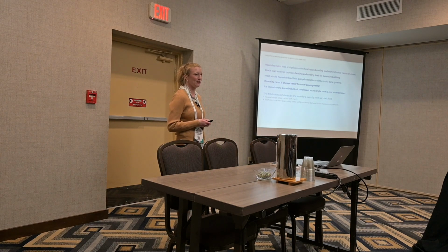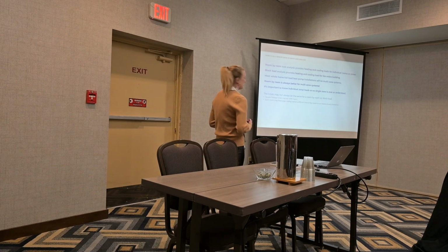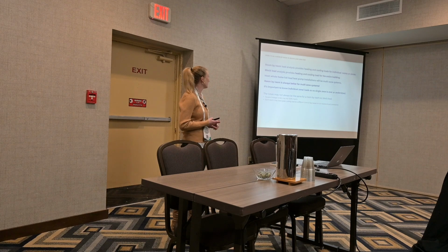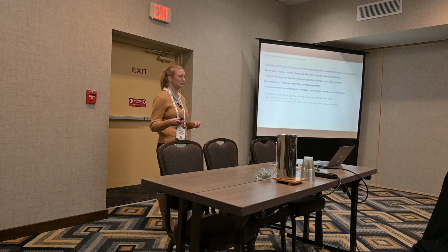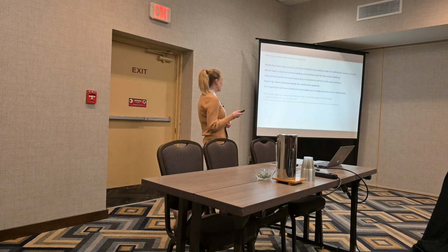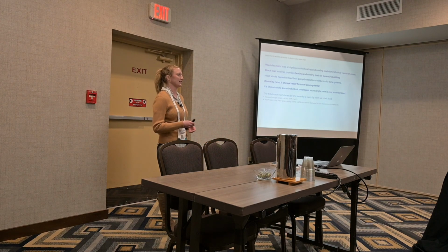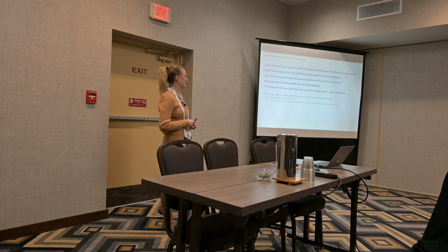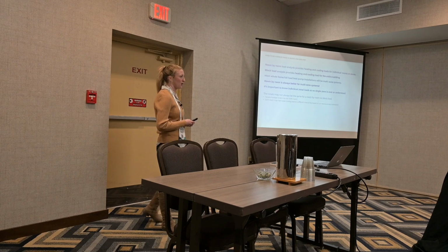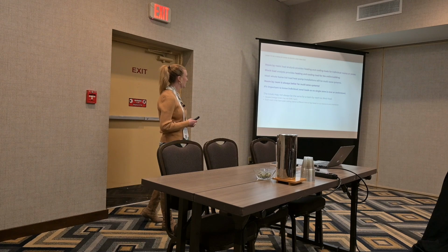All right, so now that you know how important it is to do a load calc, does it make sense to do a block load or a room by room load analysis? A room by room load analysis provides heating and cooling loads for individual rooms or zones. A block load analysis provides the heating load and the cooling load for the entire building as a whole. Most whole home full load heat pump systems are going to be multi-zone systems, so it's always wise to do a room by room load analysis.